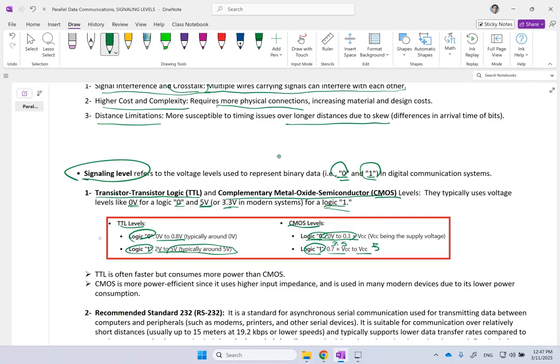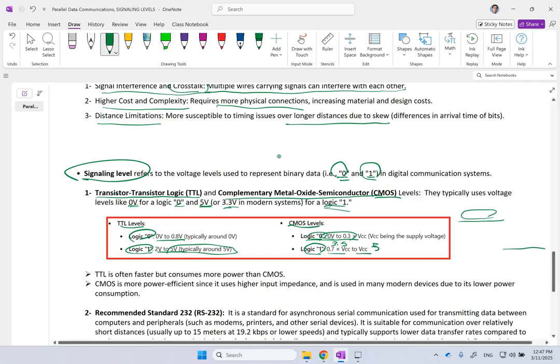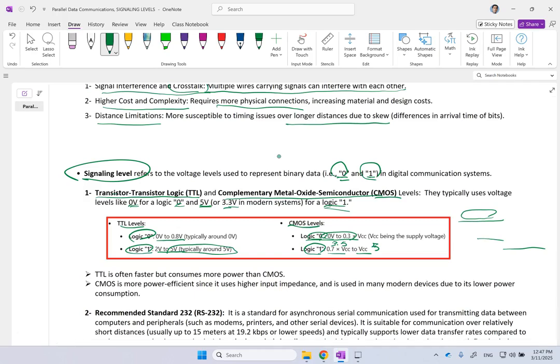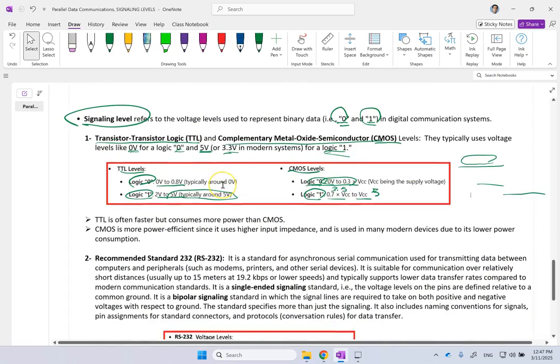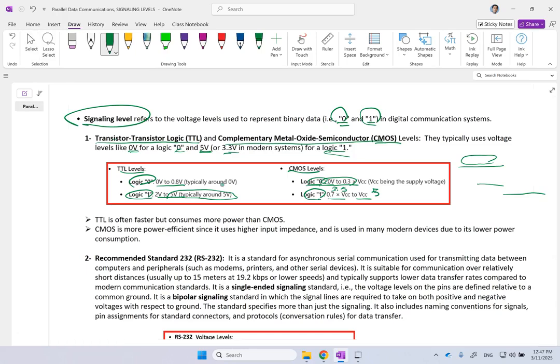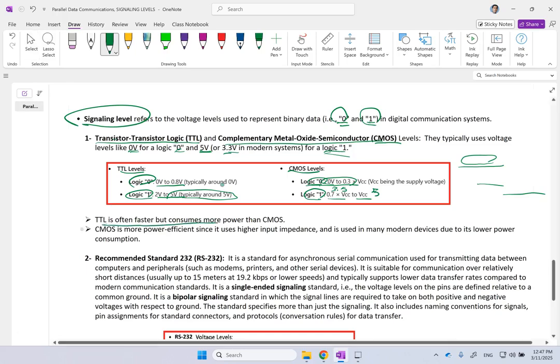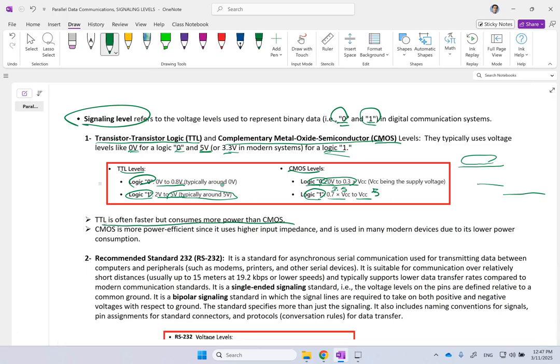And I mentioned that in one of my previous videos, that in idle situations, some of these microprocessors and control systems use idle high as opposed to idle low, because of the range that you have, different ranges and so on. Now, between TTL and CMOS, remember that TTL is basically the faster one, but it is using more power, as you can see here, right?